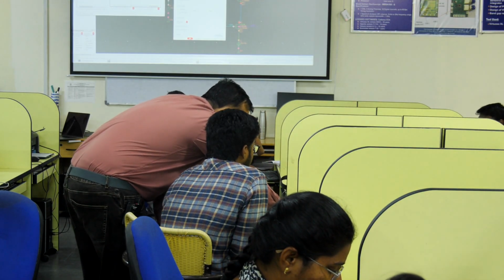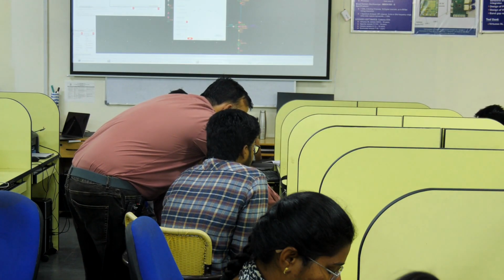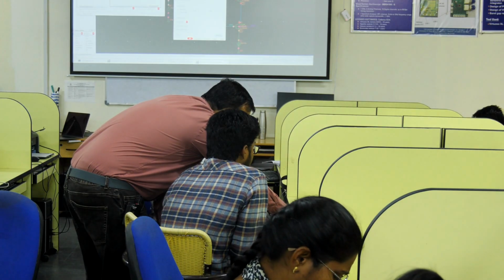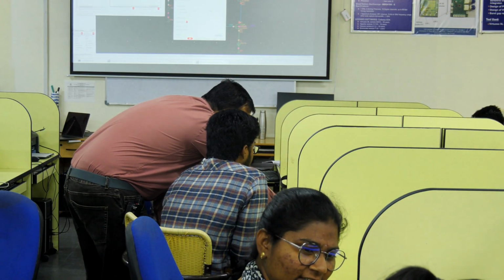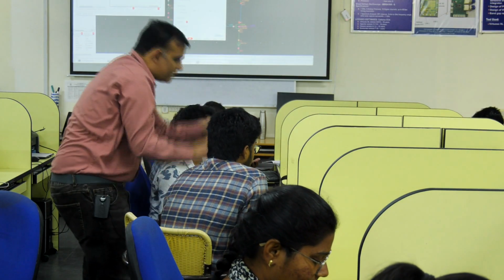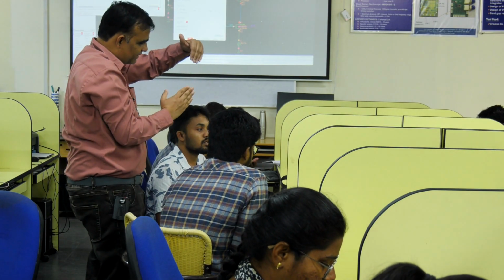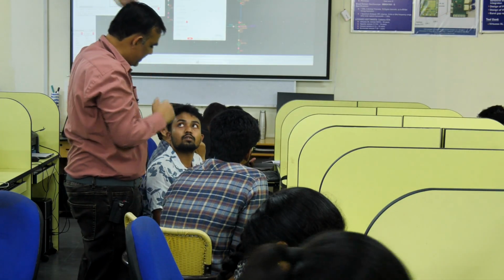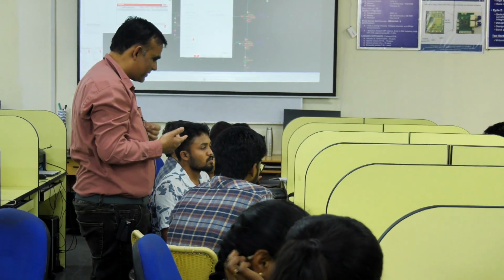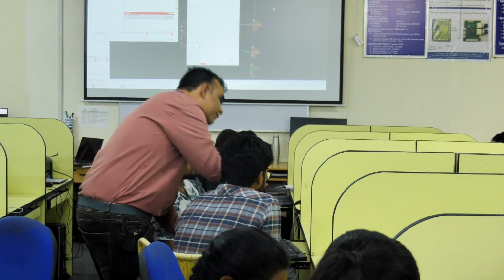Now what you need to think about is not just my pixel. So I need to think about what my neighboring pixel will be. So if I place it here, I need to give some gap for the neighboring pixel to move that side. Yes. So can I place the two transistors of this and the two transistors of this in one row? Will that be better? So it becomes a multi-dimensional optimization problem. So you need to think. Earlier you were just thinking for one pixel.